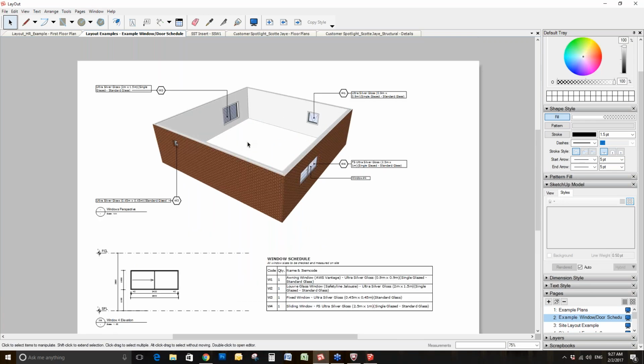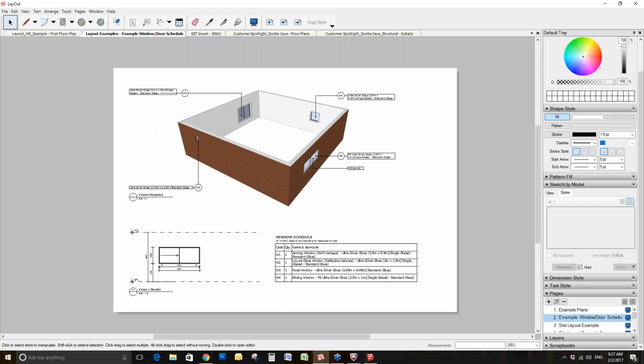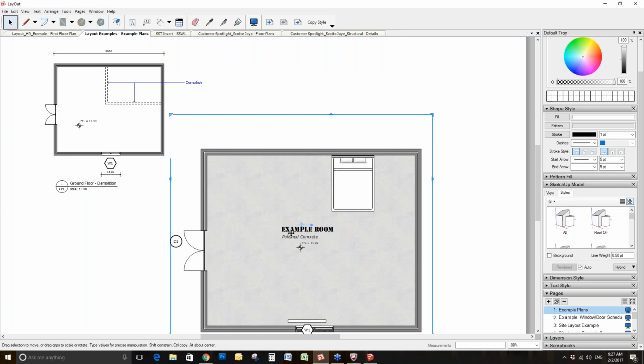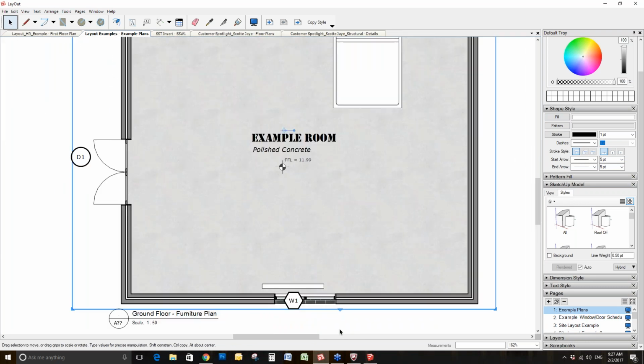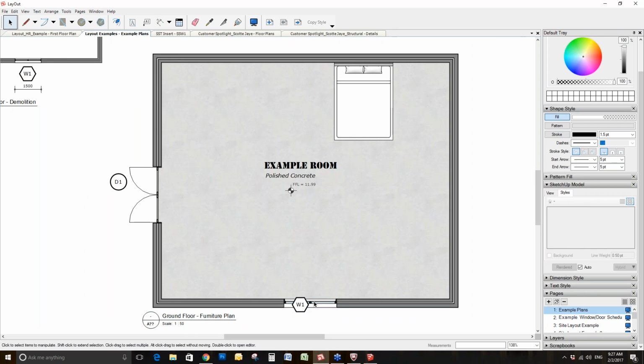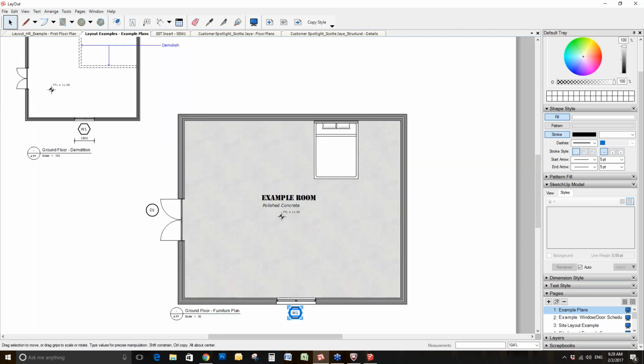There's a few other things that I want to quickly talk about. So styles, and understanding the style is really important. However, if you go back into the plan actually, you can further manipulate your line weight. And again, this is one of the big things that people don't really understand. They think that once you have brought in the model, you can't really manipulate the overall line weights here either, but you can.